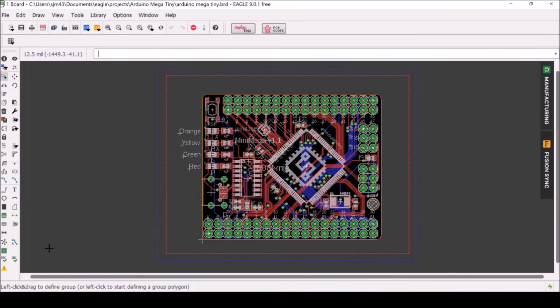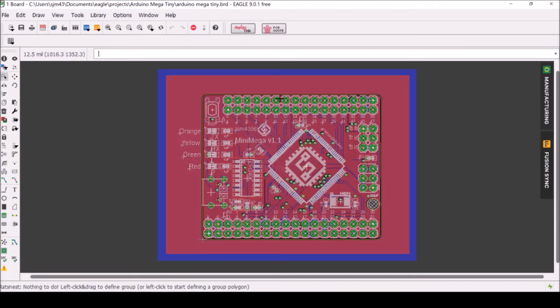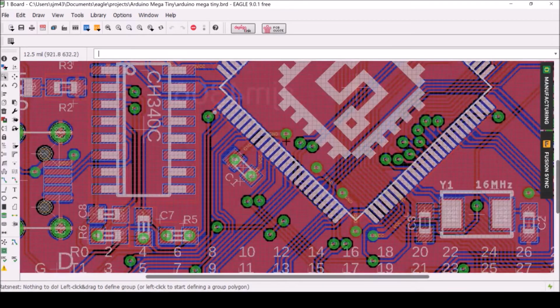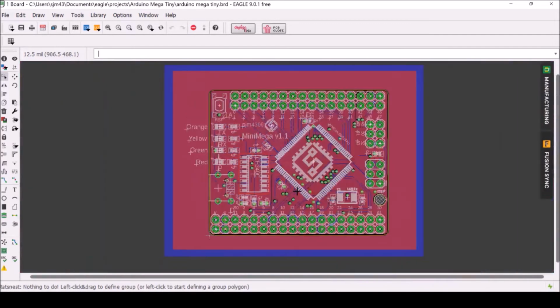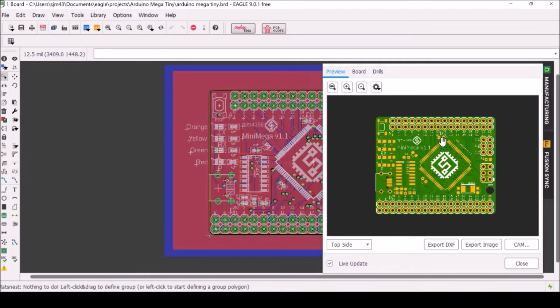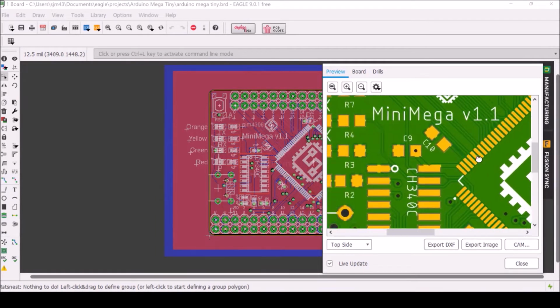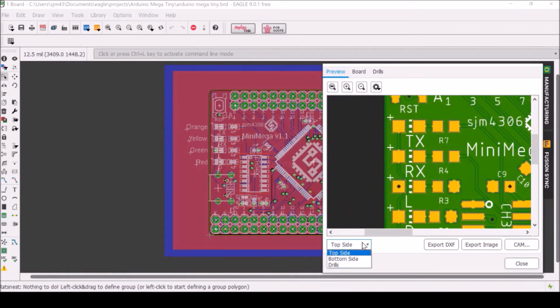Design for manufacture is basically the last step you do before clicking that order button. It's an automated check to make sure that what you design can physically be made and work as intended. Most PCB manufacturers will do their own DFM when you upload the board files onto their site, and most PCB editing software will have their own DFM checker built into it. So you might be asking yourself, why should you use a separate DFM program like NextDFM?